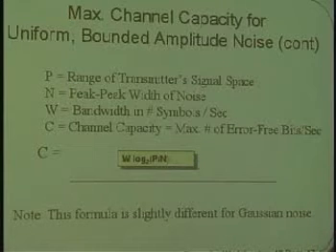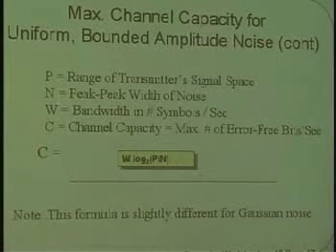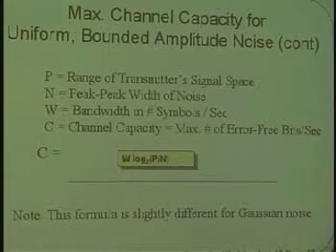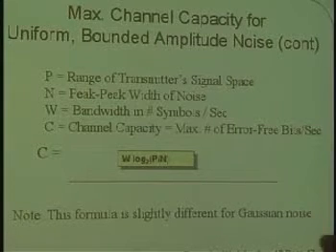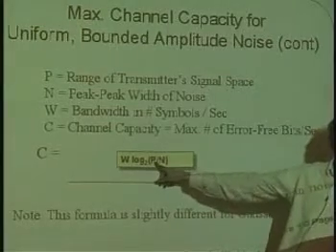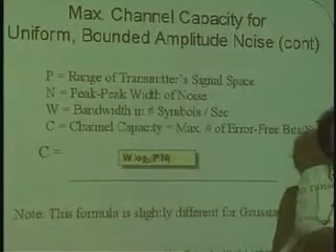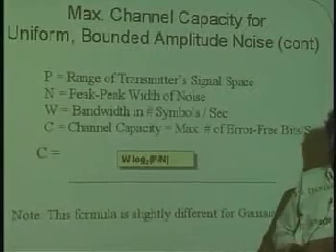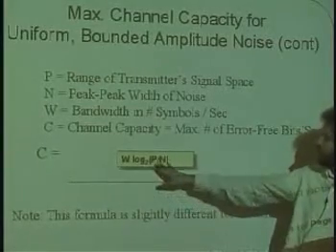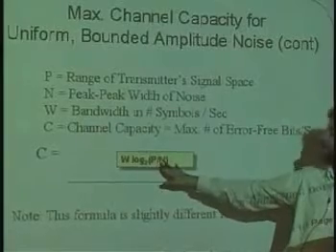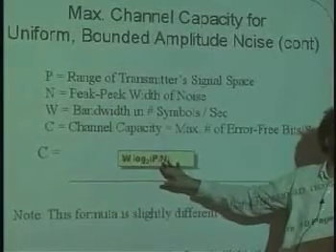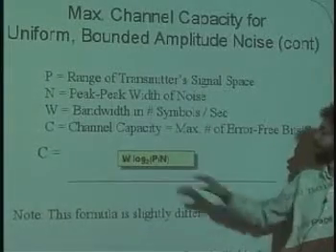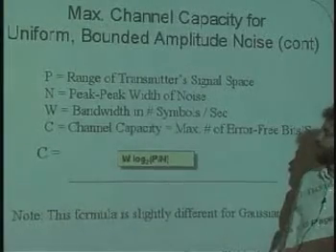This formula that's right here is the formula for channel capacity that Claude Shannon figured out. He figured out that in general, if a transmitter has a power P, which is equivalent to how large of a space it has to pick from in sending a transmitted signal, this is the length of the bar, and the noise in the channel is N, then log base 2 of P over N is a measure of how many bits you can send per symbol in the channel.